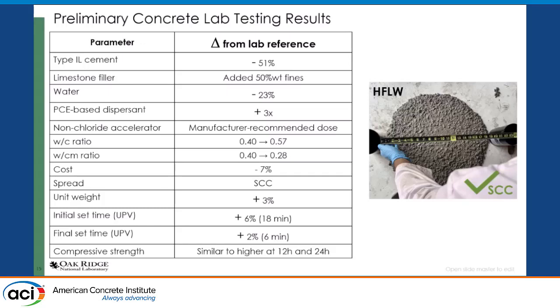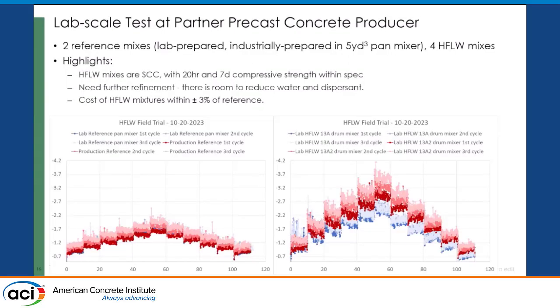It spreads as an SCC. As you can see here, it's a beautiful concrete. Initial and final set times, we measure by ultrasonic pulse velocity, and it is about the same. And the compressive strength is similar or higher with the high filler at 12 and 24 hours. So from there, we went to the plant.